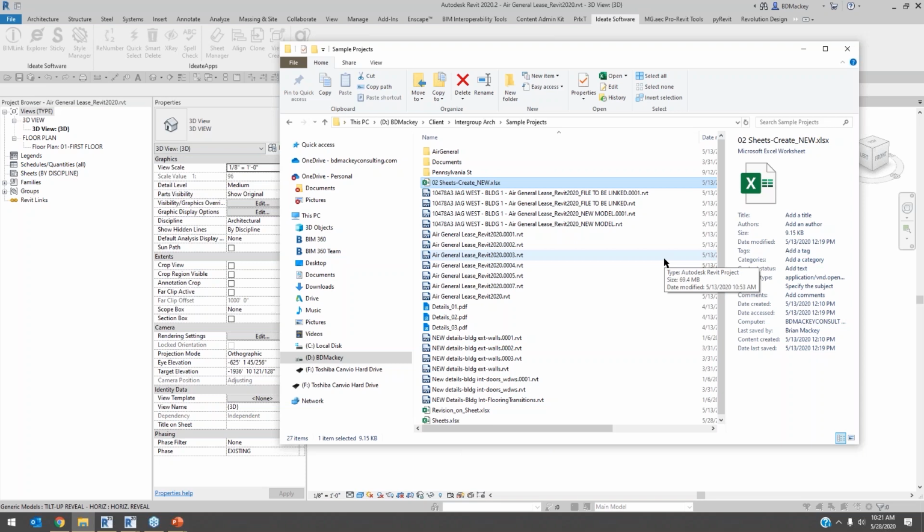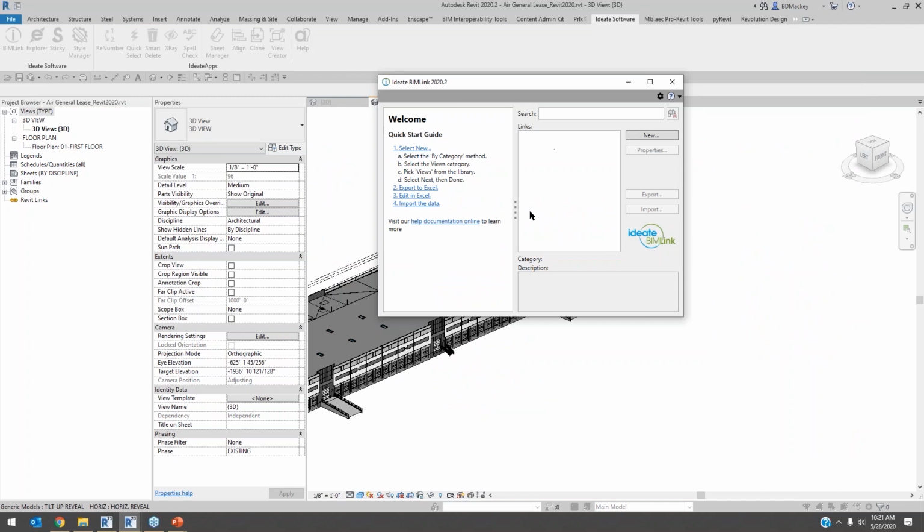put them in there, and we actually did them in different portions because the design architect did every single room in one phase, but the architect that was doing the record drawings had to do them in existing phase, new phase, phase 1, phase 2, phase 3. And so they went through and set it up that way as well. So we use the Ideate tools in several different phasings to be able to bring those through and set it up. So again, one of those types of scenarios where you can really start getting into some of these tools.